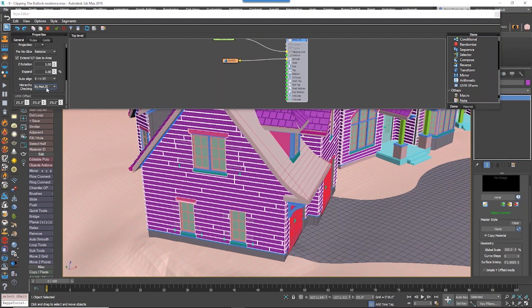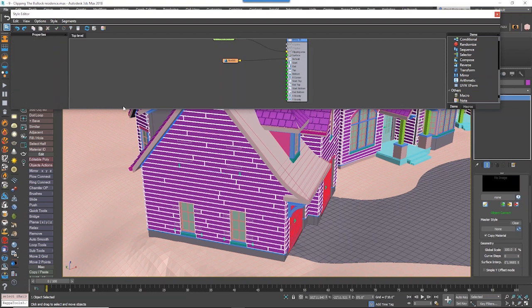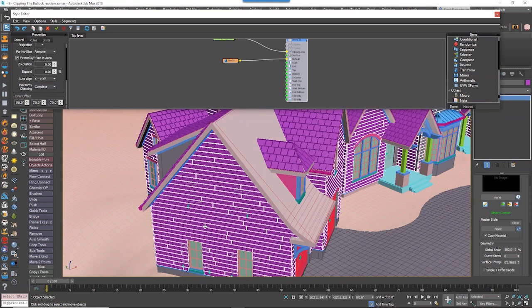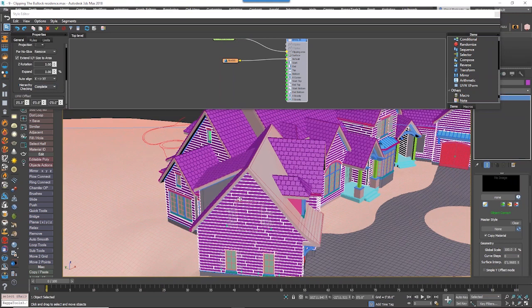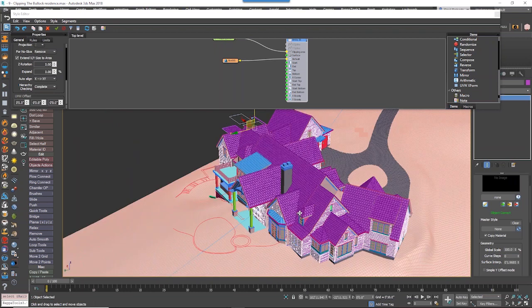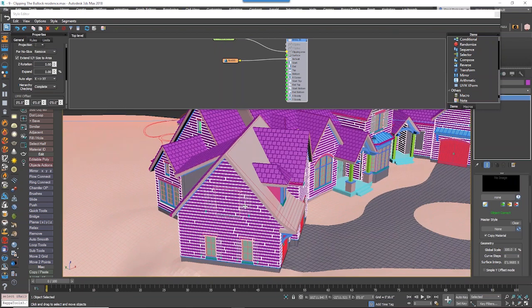There is another setting here which is worth mentioning, which is hierarchy checking by material ID. Normally this is set to complete, as we saw. Sometimes it's set to none. In this case, we have a window here which is being ignored in complete mode, because it can't quite work out if that spline that's just behind there belongs to this facade, or maybe one that's on the other side here somewhere. And so sometimes you need to give it a little bit of a helping hand.